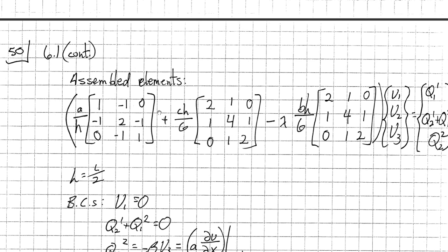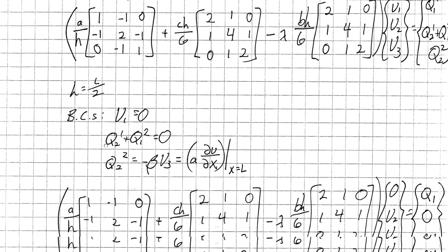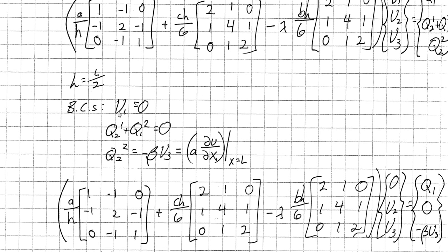So if you have forgotten how we got to here, go back, look at how you set this problem up for a single element, and then review how you put 2 elements together. So you add these up in a special way, and we get this relation. You also have this additional term on lambda, so this is our time-dependent term. You have your flux on the boundaries internally. We have 2 elements, so the length of each element is half the total length. And remember, here's your boundary condition on the left. Internally, we have no heat generation. And the boundary condition on the right is given here.